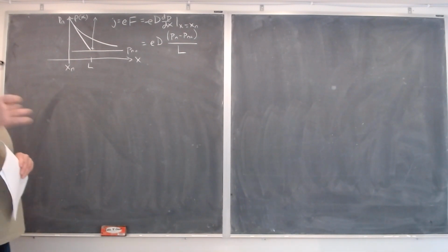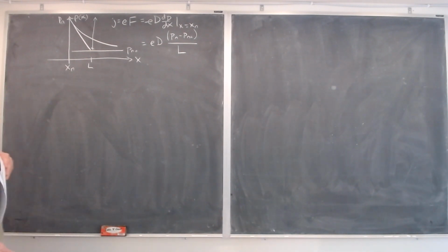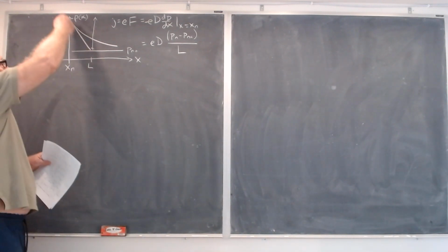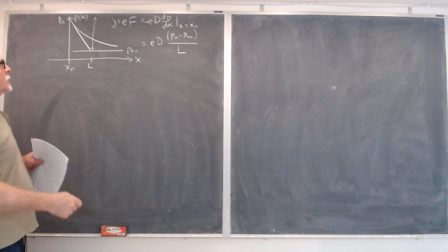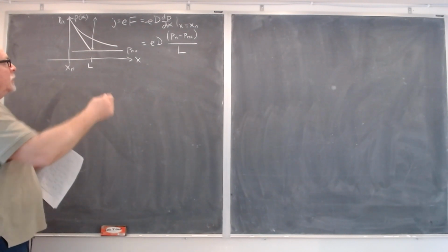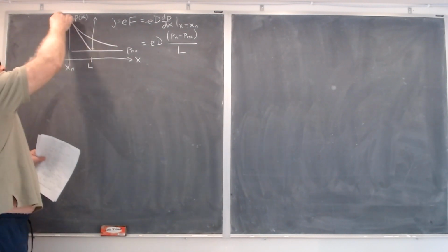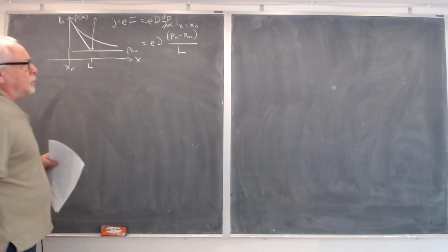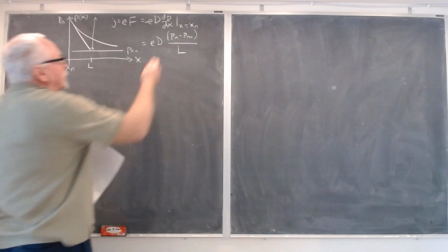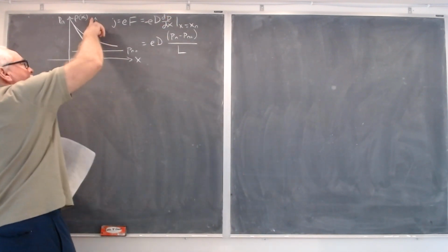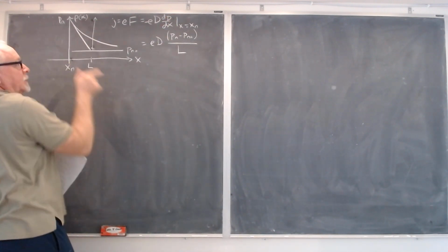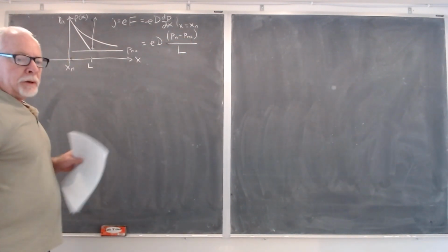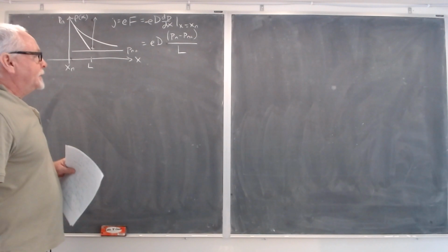Right? Okay, and you can work that out taking the derivative if you want to, but this is a way to remember it, that once you understand that you have this whole distribution there, and once you understand that the diffusion current, you're calculating this with the slope at the edge of the depletion region, which we'll talk about in a little bit, then dP dx is just Pn minus Pn0 over L. And so that's pretty easy to remember.